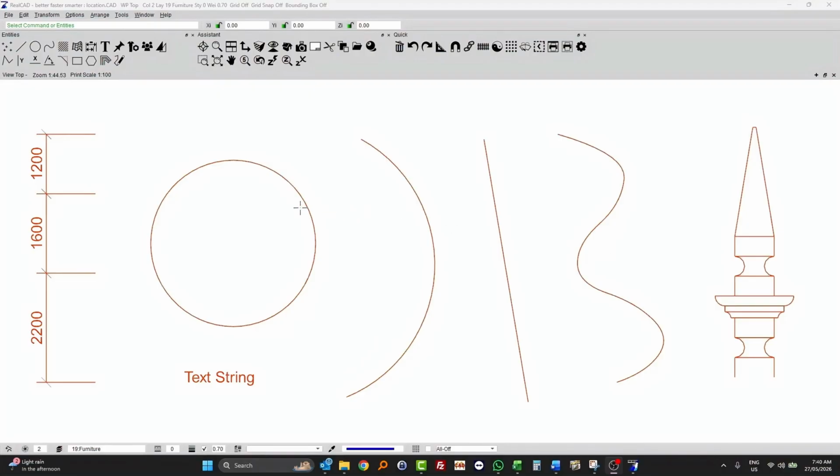In this video, we're going to explore the concept of finding points or distances or accurate positions within our geometry as we're drawing. Whilst we're drawing a line, for instance, as we hover over an object, you'll see I have a diamond cursor. If I was to click now, I am either attached perpendicular, or if I move my mouse far enough, it will turn into a tangent line position relative to the object that I selected.